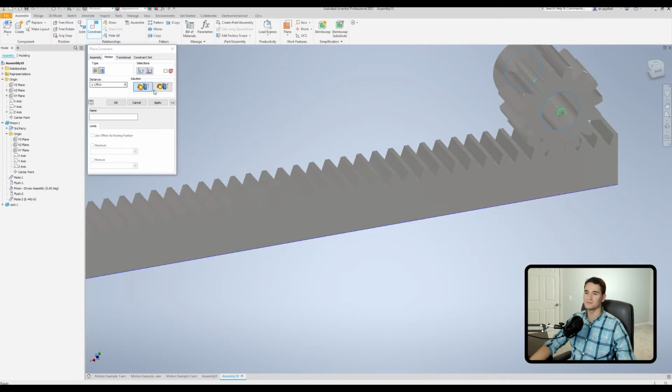That's what that number is. So let me go ahead and pause here for a moment and show you how we can find this length of linear travel for every one rotation of a circular element. So when you're dealing with a rack and pinion system like this, all you have to do is take the pitch diameter of the pinion and multiply that pitch diameter by pi. And that'll give you your circumference of that pitch diameter, which is the distance that this will travel linearly in